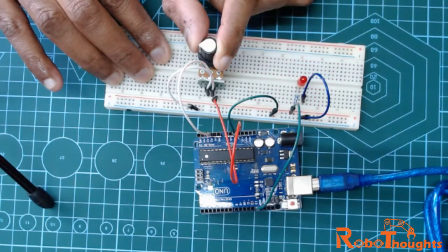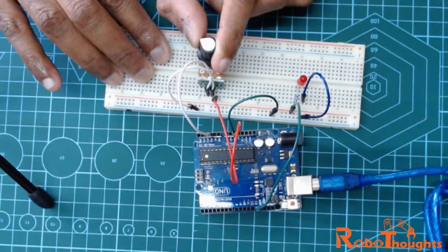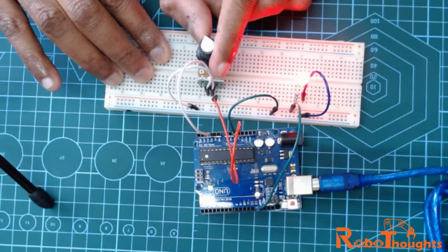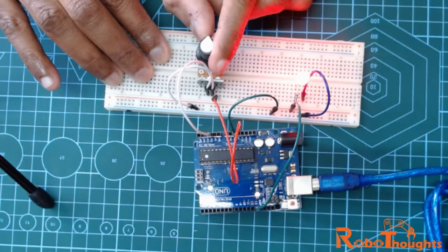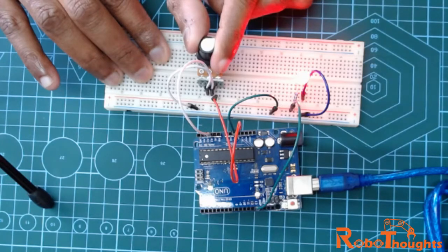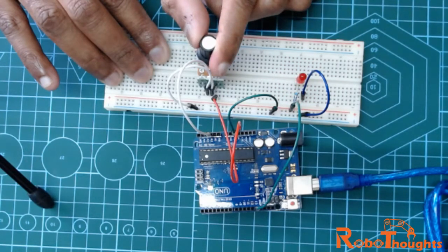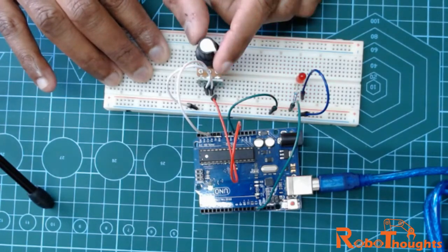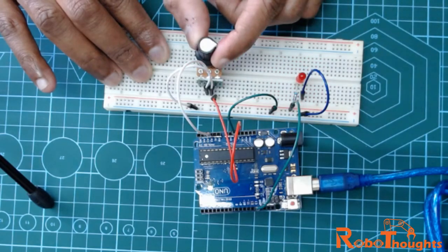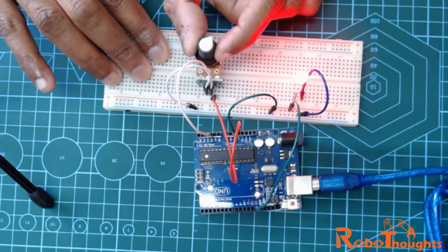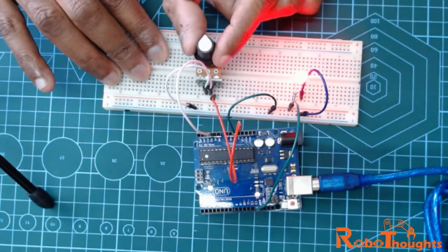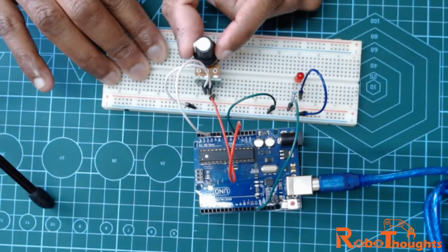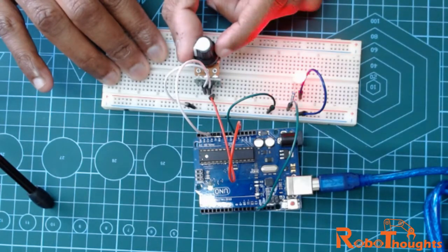Now I am going to turn it fully right and see it reduces the blinking speed, slow and steady. So the variable resistance changes, and automatically the reading from the A2 pin works as per the logic we gave in our C code. There you go. Now it's totally slow. It's at the max and the lowest. Now let me just rotate the potentiometer again. There you go. Can you see that, guys? You can see how fast the LED is blinking as the value of the potentiometer changes.